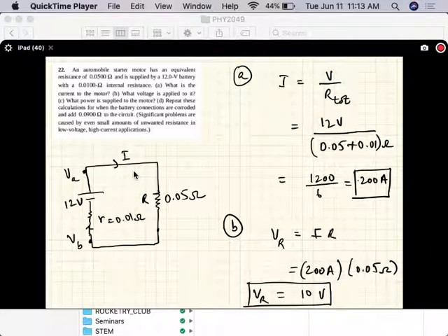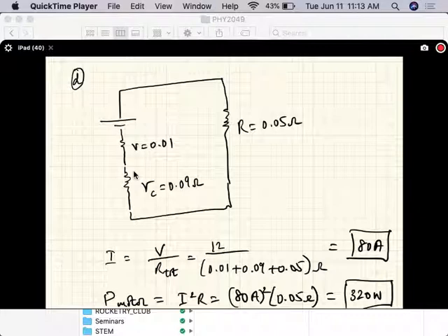So essentially what you're seeing is, if you add a resistance comparable to the load, here's the load, and this resistance because of corrosion is greater than the load, you're changing the behavior of the circuit. So this load will not perform as intended.